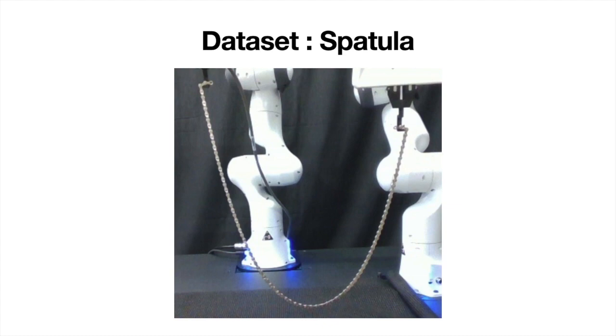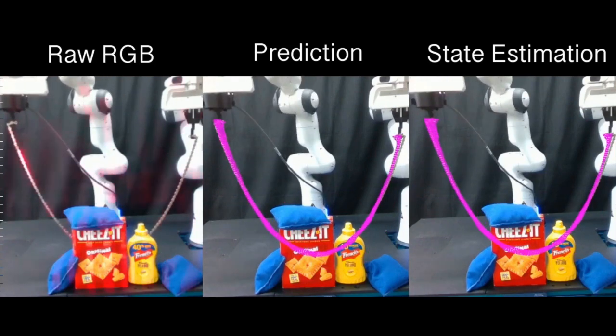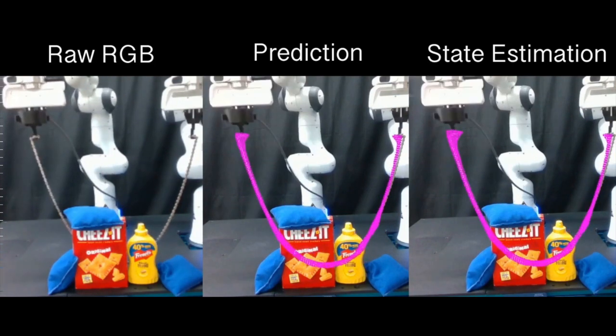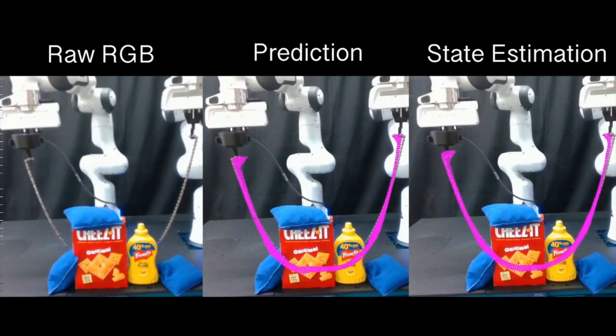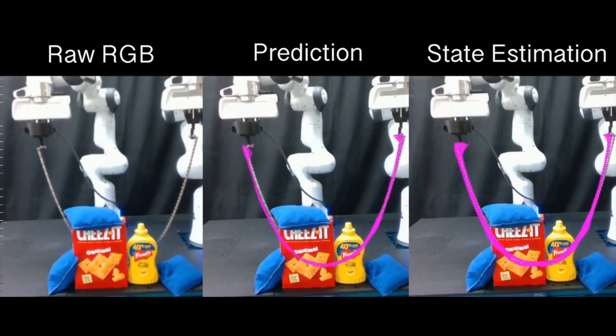Our method can also be applied to rope-like objects. We assume a scenario where a robot grasps the end of the bike chain. Here we train our model on 216 transitions inside a bounding box and test on 20 unseen transitions. End effector orientations were fixed during bike chain manipulation because geometry changes are dominantly caused by translations rather than rotation. This video shows that our model is able to predict and estimate both free space and in-contact chain geometry. The in-contact phase occurs when the arm moves sufficiently far down such that the chain lays on the table.